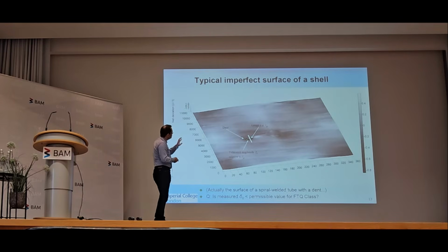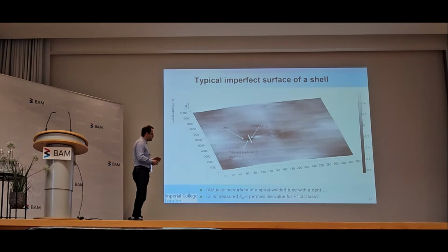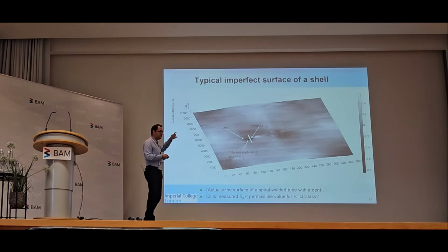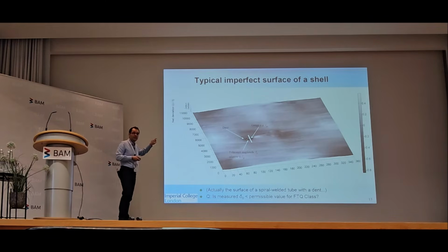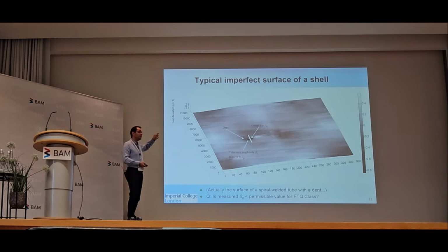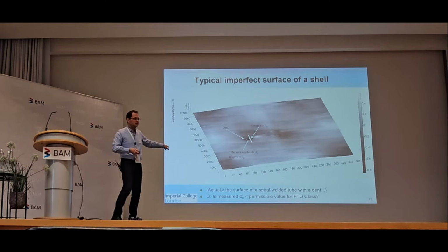And so there are different tolerances that you have to check. Let's say we're talking about the dimple tolerance, where you look for bumps on the completed structure and you place gauges of set lengths. The lengths are related to buckling cap wavelengths for a shell of that radius and that thickness. Once you place a gauge against the wall, you have created a reference axis. If you drop a perpendicular from that to wherever it hits the wall, that will give you a tolerance amplitude. And that is what the standard controls.